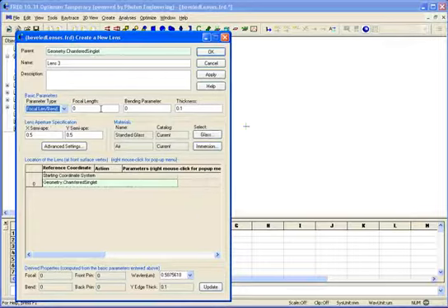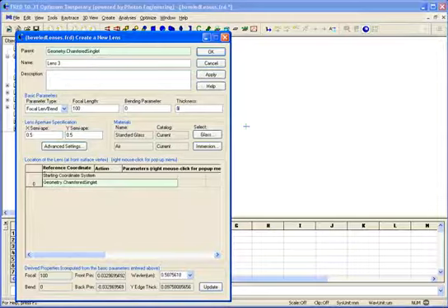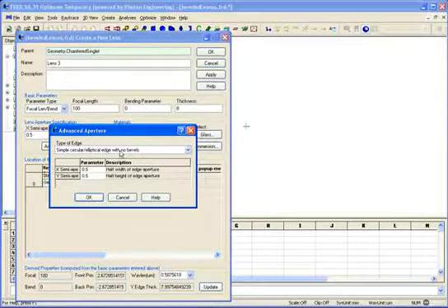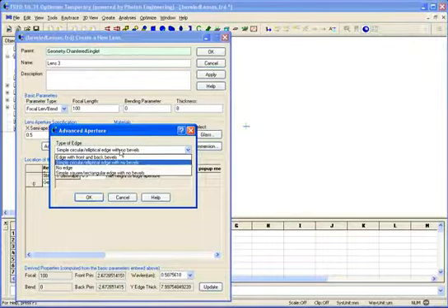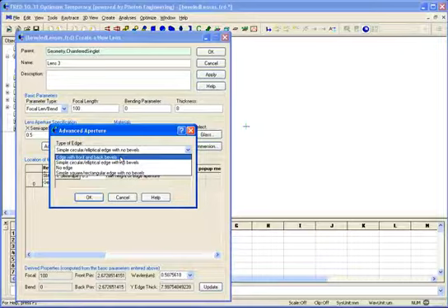I'll define it by focal length and bending, so we're going to make it a biconvex lens. Give it some thickness, 8 millimeters. Down here in the lens aperture specification area, I can choose from some advanced settings. My options are I can give a standard circular elliptical edge without bevels. In that drop-down list, I can also select edge with front and back bevels.